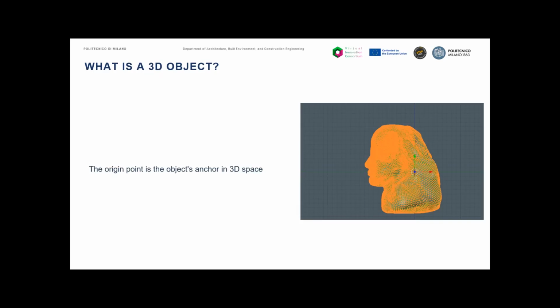Bad imports also use wrong scales, wrong center, and land in the wrong position. I mean, it's a nightmare. So it's always good to have the model positioned, placed in the point that you want. Repositioning is something semantically meaningful. It's the geometric center and also defines the floor of the contact points. It's a standard pre-processing step in any optimization pipeline, so it's pretty important.